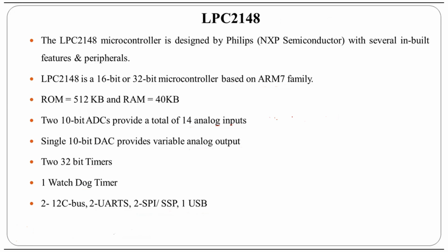It has two 10-bit analog to digital converters with 14 channels, 14 analog inputs, and one 10-bit DAC, digital to analog converter, and two 32-bit timers, timer T0 and T1, corresponding to port 0 and port 1. One watchdog timer is available.